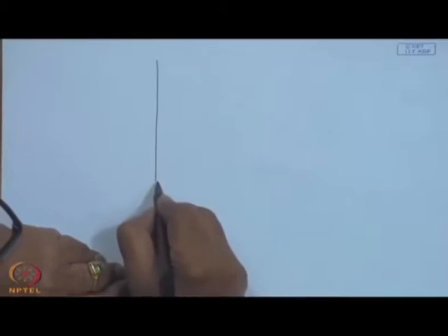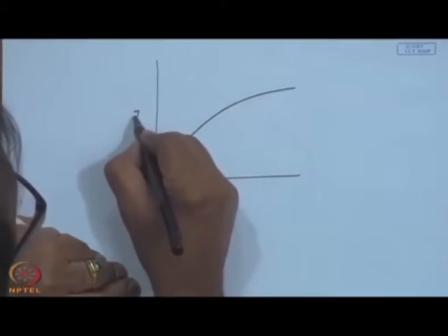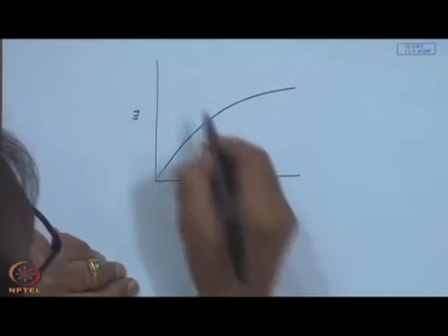So, ultimately, having done this, we want to know the performance so that the size of the system can be decided. If you have got 16 gigajoules of load, how much area you have to put. We have already given sufficient logic to say that the performance is not linearly proportional to the area of the collector, but it is monotonically increasing with a negative second derivative, a convex upwards curve of this particular form. So, if I plot the solar load fraction F versus the area of the collector, the main variable.